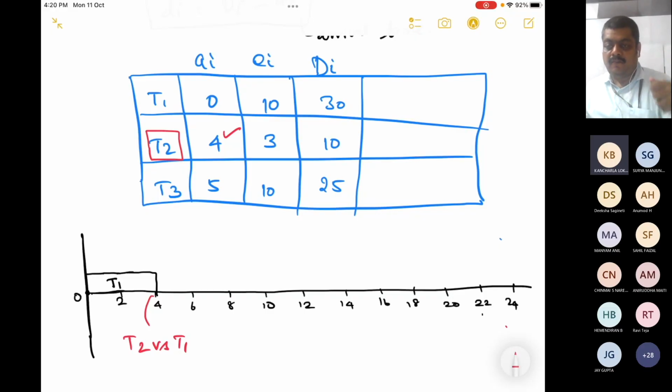You see that you have a very big baggage and it will take a lot of time, so you give him the CPU. Okay, no problem, you carry on. But in an embedded system, if a new task comes with an earlier deadline, the running task will be stopped in between, and that task will continue. Till then you will be suspended, or preempted, as we call it.